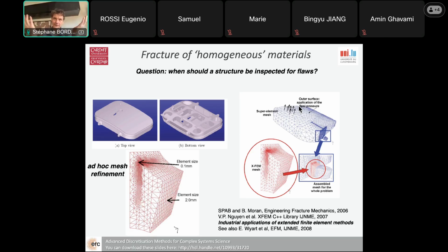Why is it higher? Because at 30,000 feet, 10,000 meters, the pressure is much lower than it is on the ground. And in order to breathe, you have to be under approximately the atmospheric pressure. 9 psi is a bit less than the atmospheric pressure, which is also why if you go on a flight, you tend to swell because the pressure inside the aircraft is a bit less than the pressure you're used to. That's why if you have certain conditions like heart failure or problems with your capillaries, you need to be careful when you are in slight depression, under pressure. I mean, under meaning less pressure.